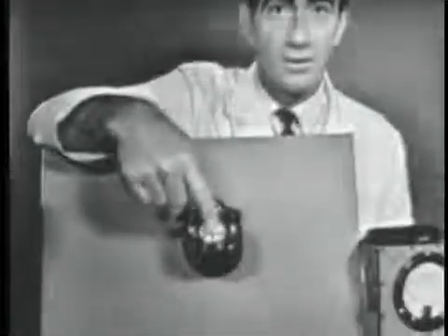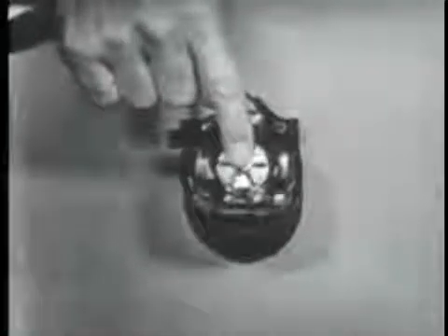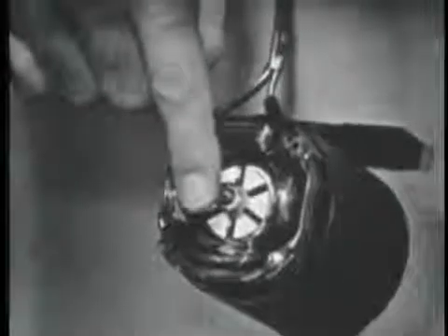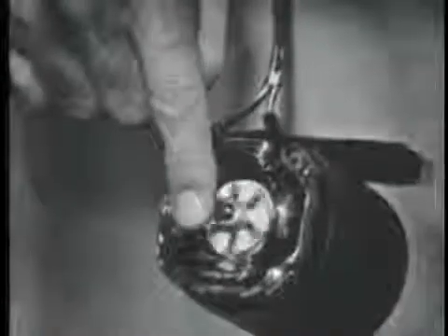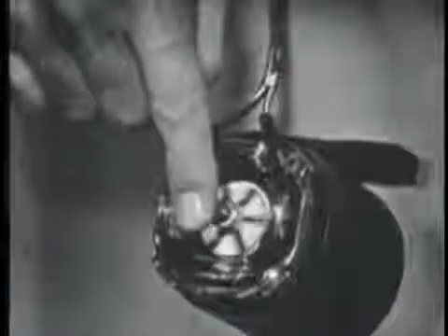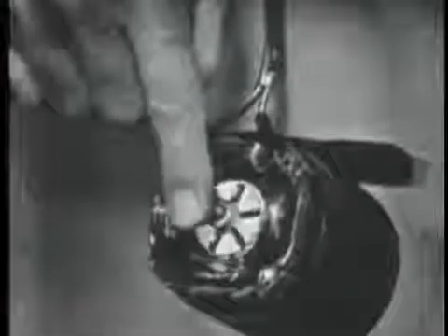Now, that's why the rotor can continue to turn the fan. The load of the fan causes the rotor to slow down, just as I can do with my finger here. I can cause the rotor to turn slower. Now, as it slows down, the slippage increases, and the frequency at which the conductors of the rotor are cut by the rotating flux lines increases. More current flows. The magnet becomes stronger and compensates for the increased load. Now, there's a limit to this. I thought there would be.